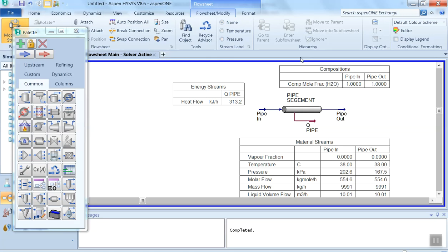The main source of error in this case can be the use of the wrong fluid package, that is, we can call it an algorithm error. Incomplete data insertion can also lead to incomplete simulation, which can be minimized by proper data preparation before starting the experiment.